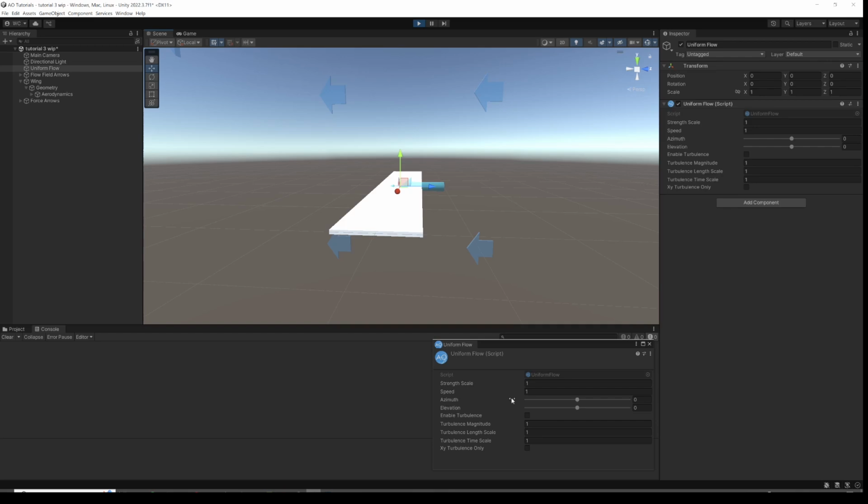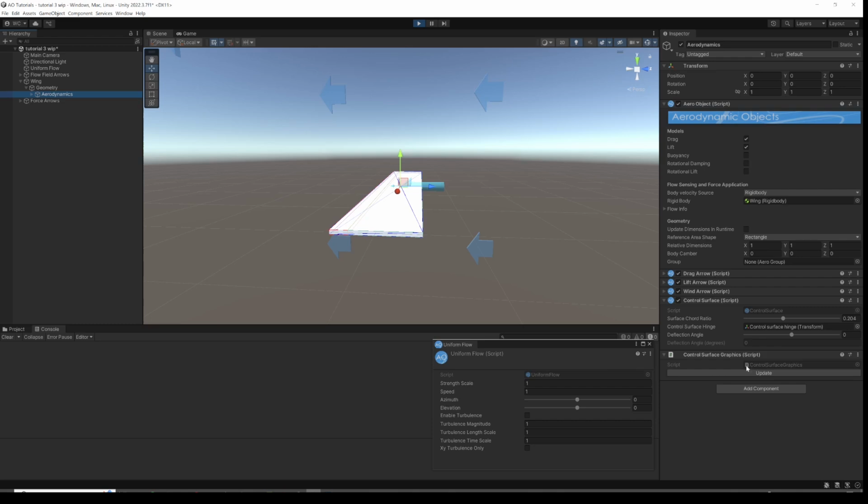So if we now try changing the control surface, so I'm deflecting it down, and there you can see magically the lift is going up. And if I do control surface trailing edge up, that makes the lift go down. Okay, and that's how you control a plane in flight. You're not changing the actual angle of attack, you're changing the relative angle of attack using a control surface, and that's what changes the lift on the surface, and that's what makes a plane. That's how you control the plane.